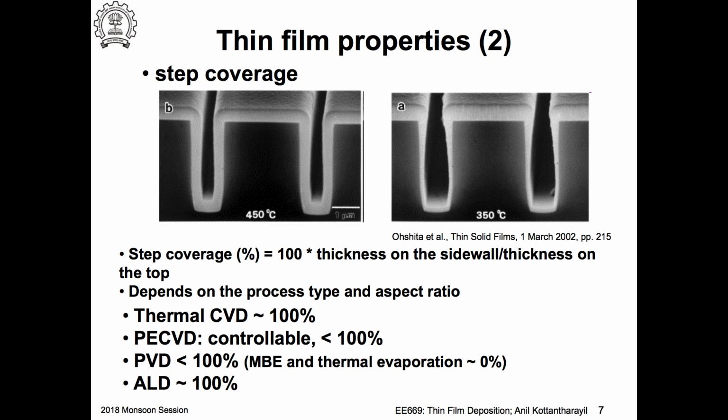Suppose I want to run a conductor, a piece of metal line through such undulation. Which one would I prefer? I want to just connect two transistors on the chip, and the metal has to run through some uneven topography, right? So which one would I prefer? That one, because this would result in a higher series resistance, right? A thinner film, higher resistance. What are the other problems?